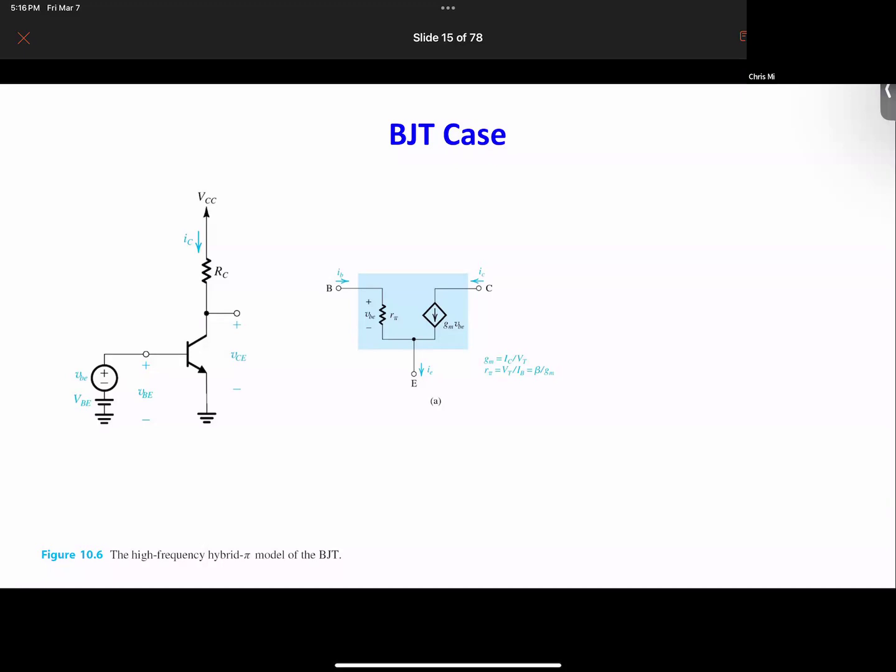With only three pieces, the maximum you would have is three capacitances. Because the base is in the middle, the collector and the emitter are separated by the base. Therefore, this capacitance is typically small and can often be neglected, so we often only look at these two.